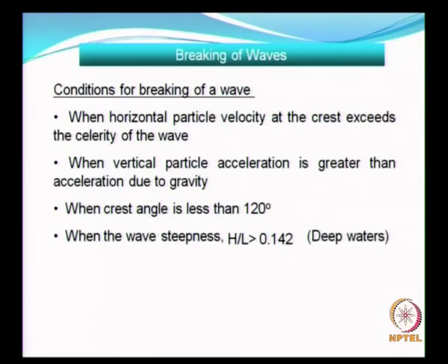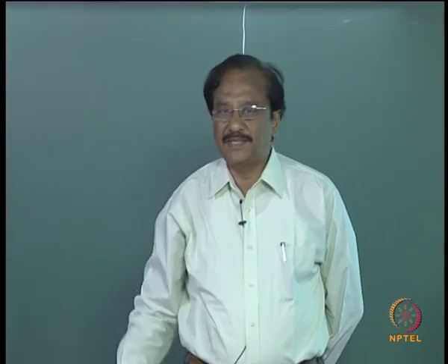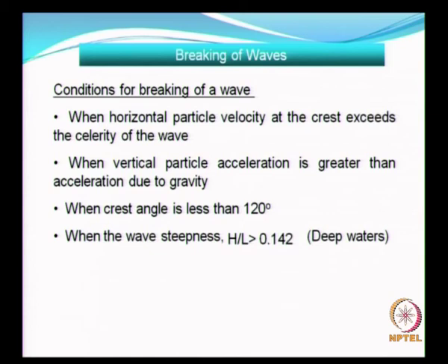So, let us look at the breaking of waves. There are several conditions: when the horizontal water particle velocity at the crest exceeds the celerity, that is, the velocity corresponding to the crest of the wave exceeds the speed of the wave; when the vertical particle acceleration is greater than the acceleration due to gravity; when the crest angle is less than 120 degrees. That is another criterion. It is not that popular.